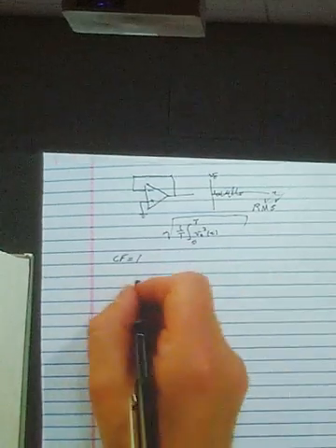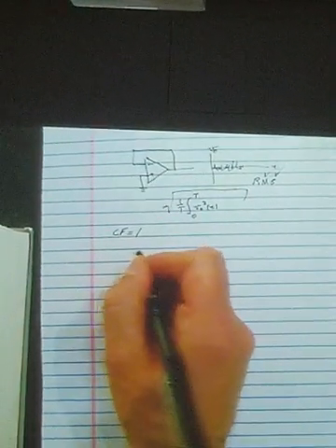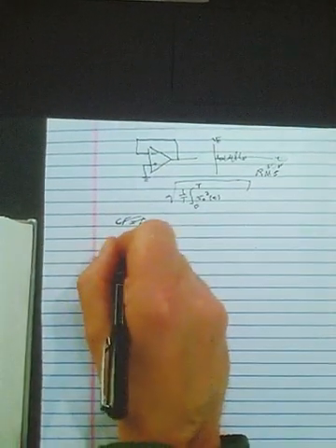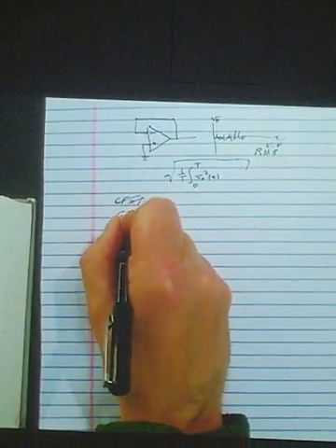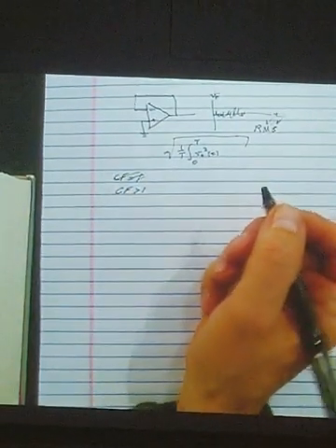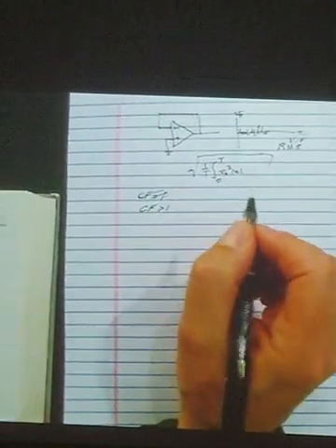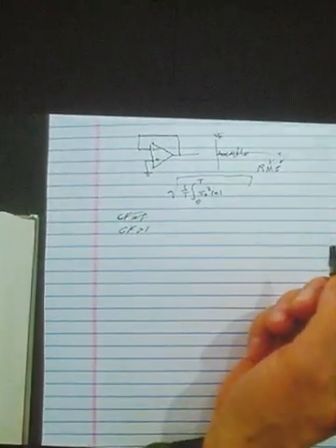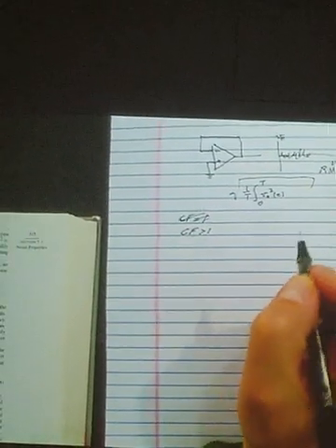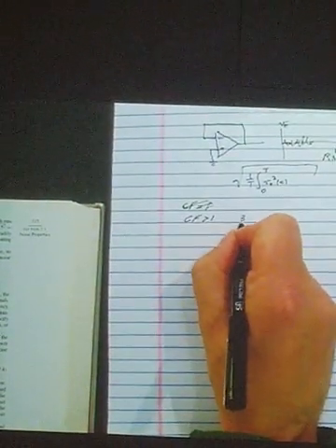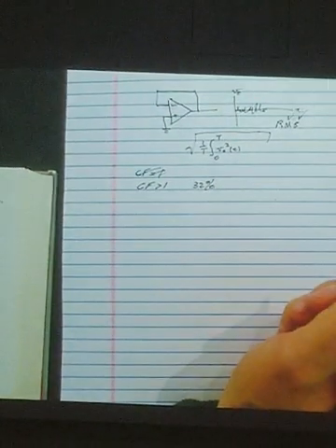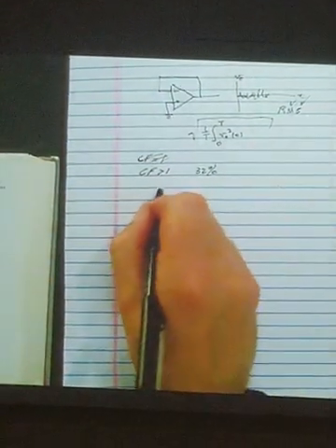Or put it another way, what percentage of the time is the crest factor greater than 1? In other words, what percentage of the time is that voltage bigger than its RMS value, our hypothetical 1 millivolt? Well, if it's Gaussian, it's about 32%. So about a third of the time, that signal exceeds.